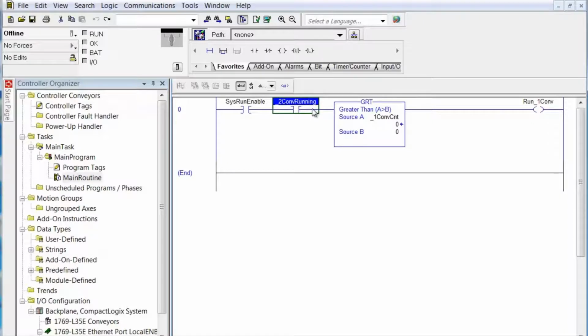So anyway, two conveyor running is not something you control. It's a condition that you are acquiring from another controller from a downstream process. So if two conveyor is running, you could rename that, we want product, we want cartons. Whatever it is you're supplying, the downstream part of this system, it wants it. So you could call that product request. However, the way that it requests the products, it turns on the conveyor, gave you access to the aux contact, so you know that it wants product.